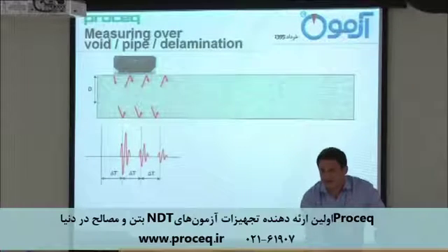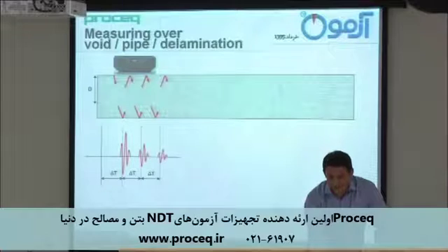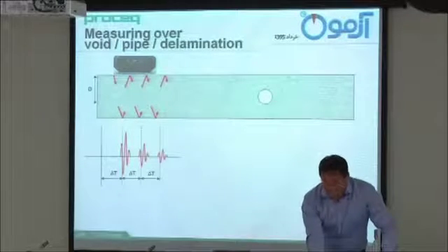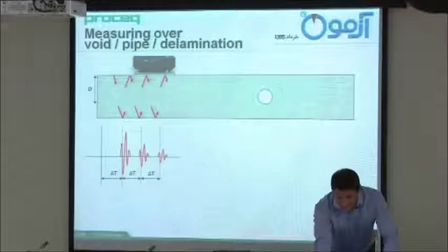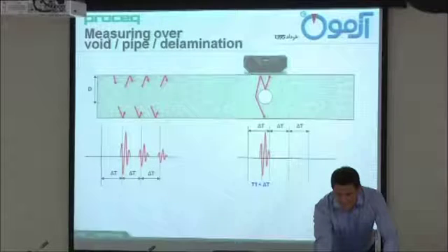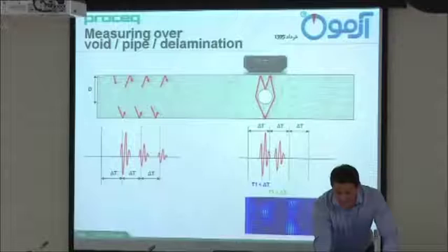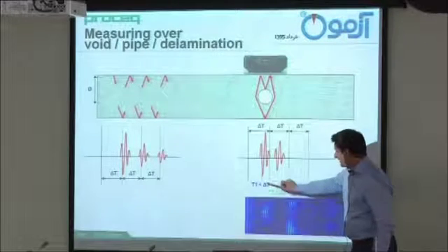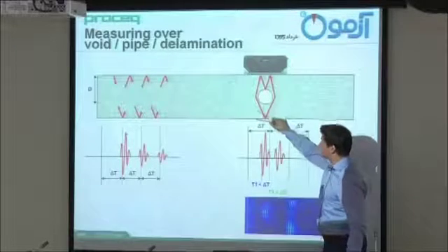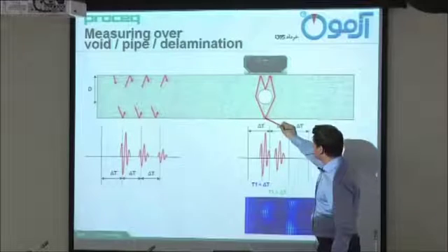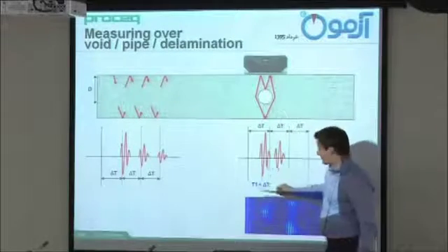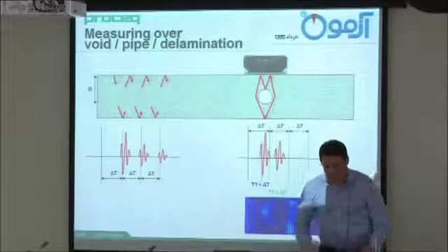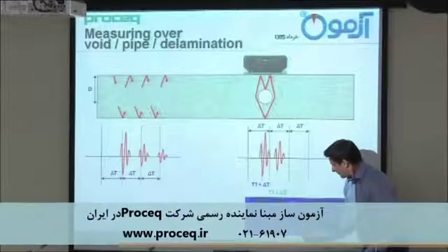So when we talk about not testing dimension, distance, but checking voids inside, we have seen first, air is a big reflector, like our mirror back home in the morning, and the steel is not as big. What happens here? You will get these signals. Then you can see the green one, and this is a typical shape. Can everybody see this shape here? Here you have the blue. This is the first, so it is too short for the back wall. Then this is a longer distance as usual, because it has to go around, so you get it a bit wider. And then you have the next one, what is coming because of going back. So you get this, it's called the back wall, and this is the void.